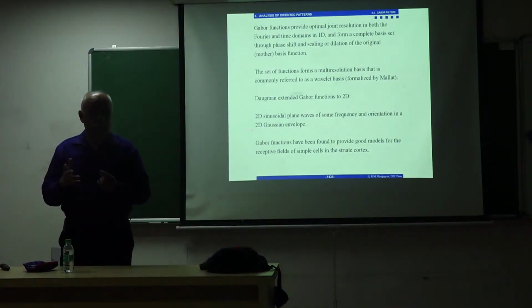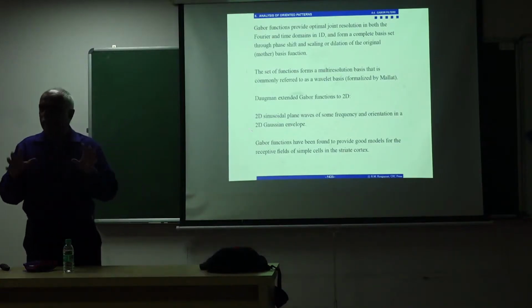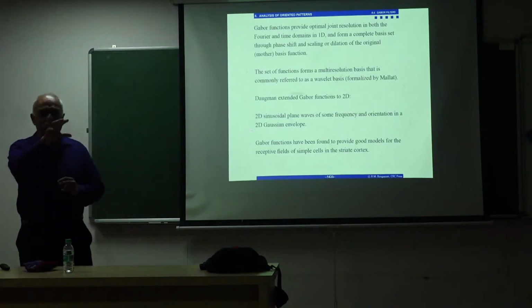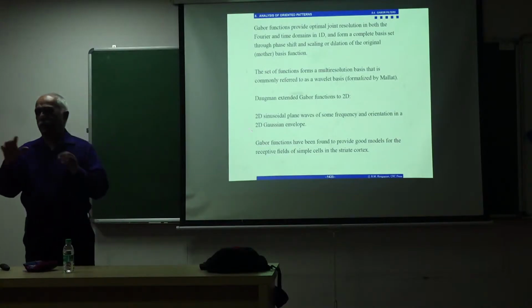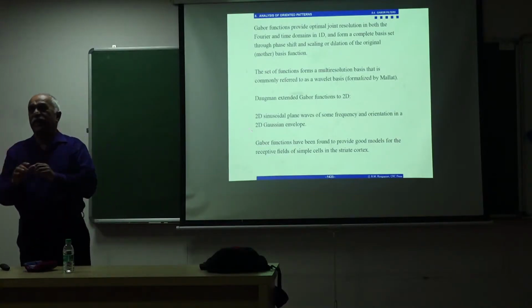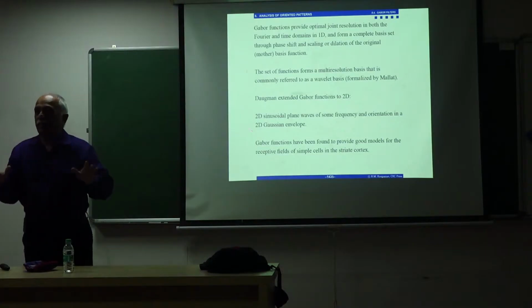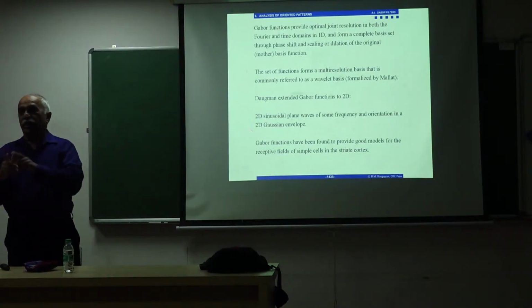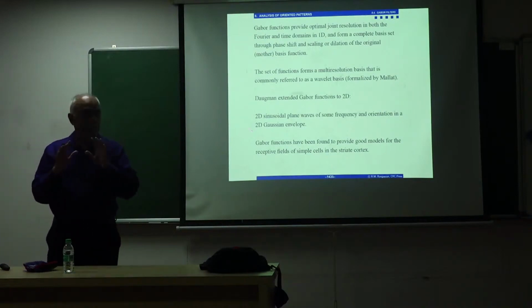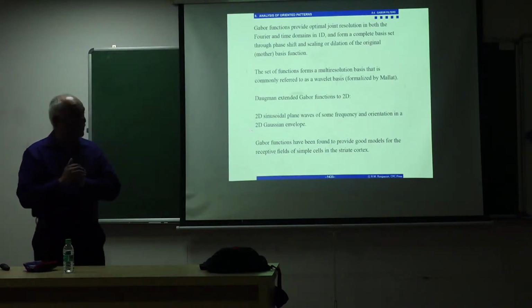That's what is done in wavelet analysis. You take a finite set of wavelets, and from experience or experimentation, you know these wavelets of such and such scale factor and bandwidth or frequency will be enough for this application. And you use only those. You cannot go back to the original signal from those limited components.